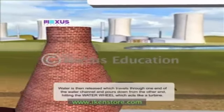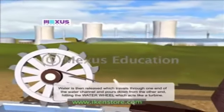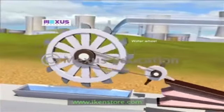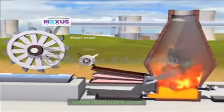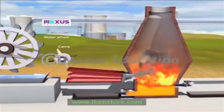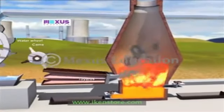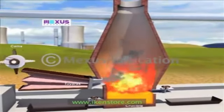Water is then released, which travels through one end of the water channel and pours down from the other end, hitting the water wheel, which acts like a turbine. The water wheel starts rotating due to the pressure and the flow of water, causing the mechanism of cams to also move, eventually striking the tuyeres to bellow instantaneously. Thus, preheated compressed air is introduced at the bottom through tuyeres, entering just above the crucible.